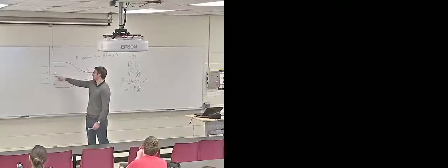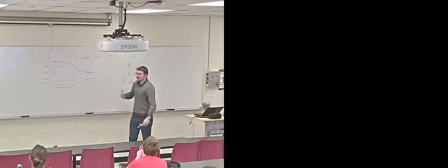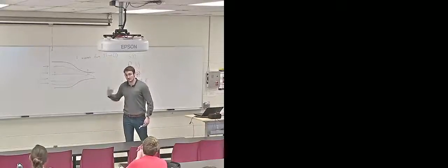And so the idea here is that we have dV/ds, that is the rate of change of the velocity along the length of the streamline, not with time. But because V is convecting that particle along that streamline, it's going to start seeing an acceleration induced by the changing velocities in space.